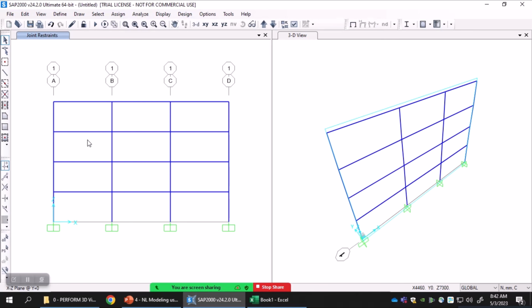Now currently this is a linear model. We have no plastic hinge in it, or no inelastic component in it. So this will behave linearly. For example, for any beam at both ends, the relationship between bending moment and the rotation theta is forever linear. So if I apply some force P, a horizontal force, which is unrealistically high, this model will give me an unrealistically high theta value or deformation value or any other response.